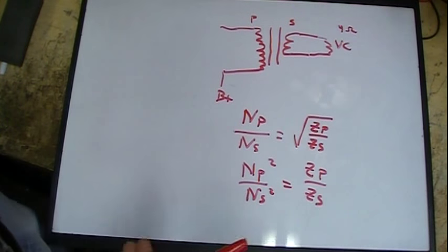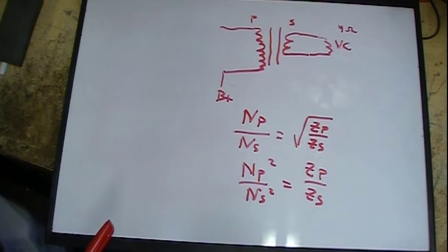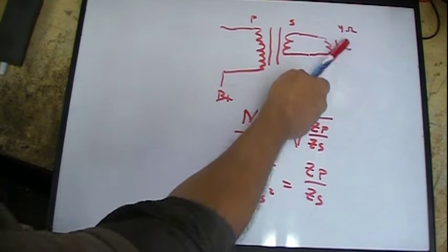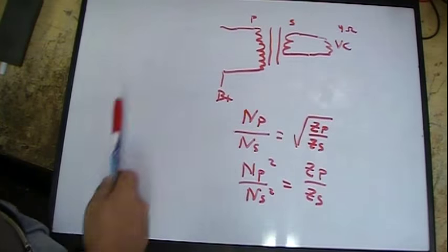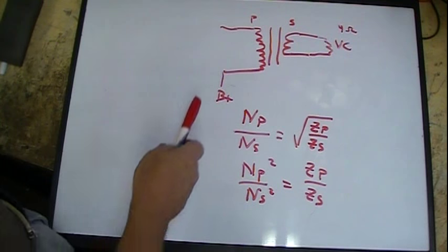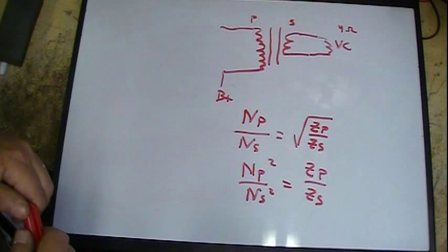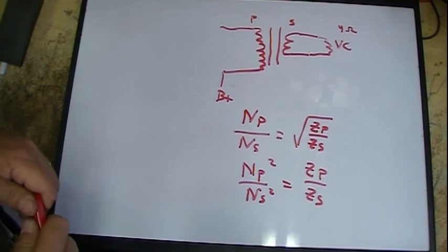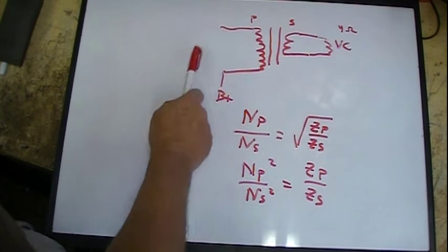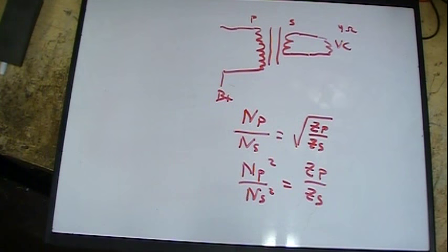The few things that you really need to know if you were actually designing something, or if you had to replace a transformer, is a good idea of the general amount of impedance that's on the voice coil, like a 4 ohm speaker or whatever, and the tube you've got, what impedance it's looking for in its plate circuit for load, and that's in the tube manual. So once you know those two things, then you can figure out what turns ratio transformer you need.